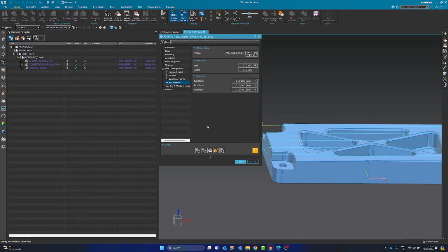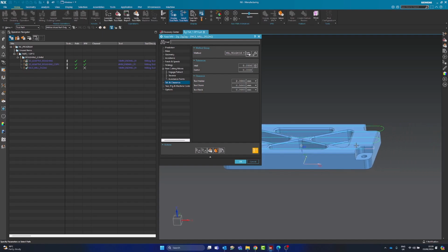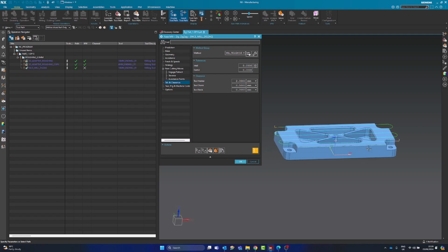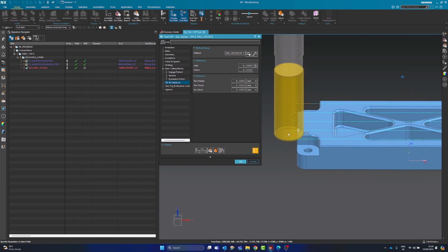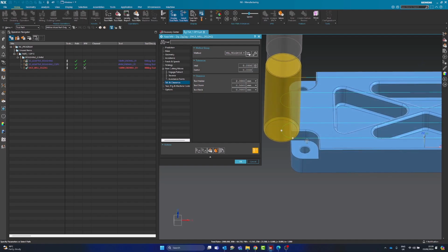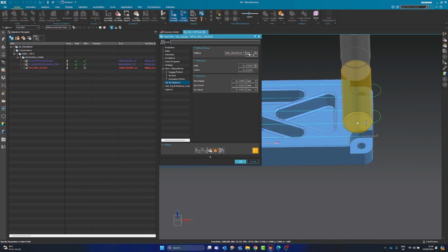My approach to building toolpaths is I like to just get something on the screen to begin with. So you can see now I've got something on the screen. Now I can begin to work with it. So what don't I like about this toolpath? If we drop ourselves, you can see we're not running off completely. That's okay in this case, but I'm not the biggest fan. I would like it to maybe run off completely.